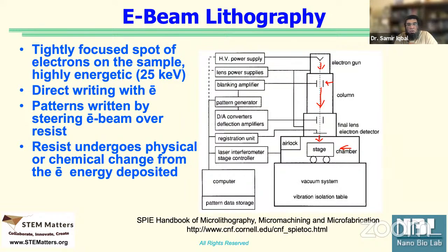We're talking about E-beam lithography. Yes, we are looking at the sample, but here the goal is to use that beam to write a pattern, right? So we use the focused beam of electrons to draw custom shapes on the surface, which is covered with the E-beam resist, right? So now again, same thing, exposed, not exposed. The exposed area will get washed away, and the not exposed will stay. You take the next step to do your development, and whatever the next step is, maybe etching, maybe doping, maybe deposition, right? The standard things.